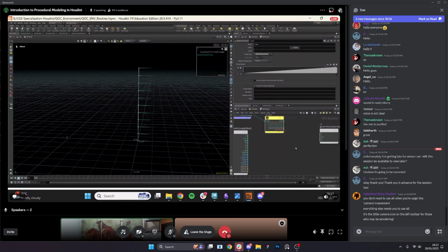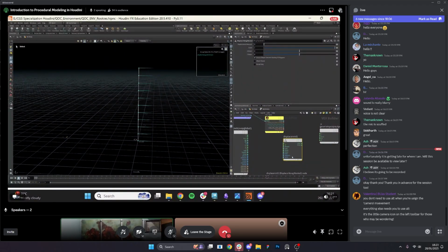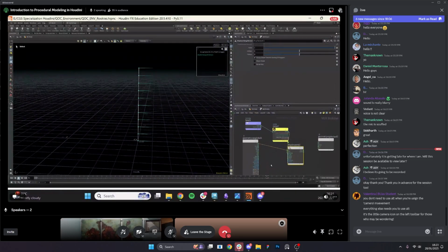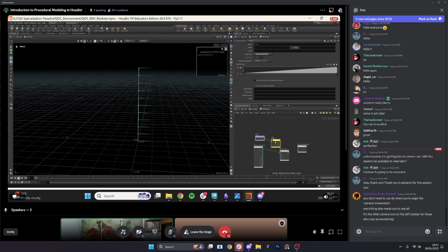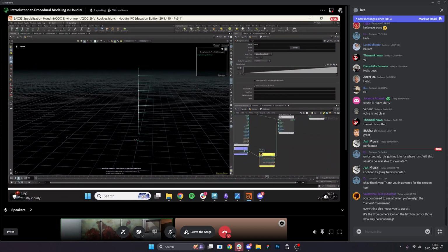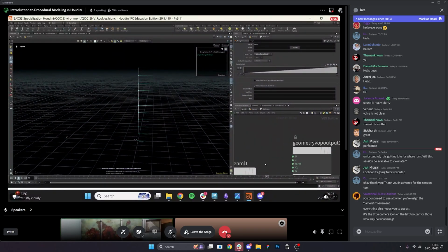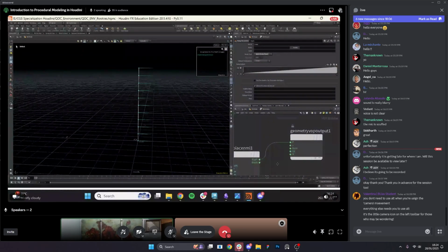And then because Houdini is brilliant, we've got a displace along normal. Now, what does that mean? It basically means, for those of you that have done a bit of texturing, it's basically a displacement map, except, yeah, let's keep it simple. It's basically a displacement. So point or P goes into point and ramp goes into amount. We'll quickly move this down because it's a bit in the way. Also, if the wonky lines bother you, you can press Shift S to get nicer flowing lines. And then, yeah, displacement goes into P.